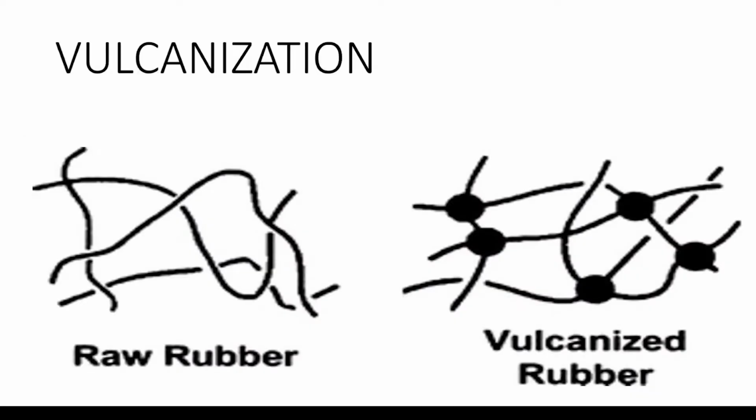vulcanization. Yan, vulcanization process. Vulcanization completes the rubber production process. Vulcanization creates the cross connection between the polymers of rubber, and the process varies depending on the requirements of the final rubber product. Fewer connections between the rubber polymers create a softer, more pliable rubber. Increasing the number of cross connections decreases the elasticity of the rubber, resulting in a harder rubber.